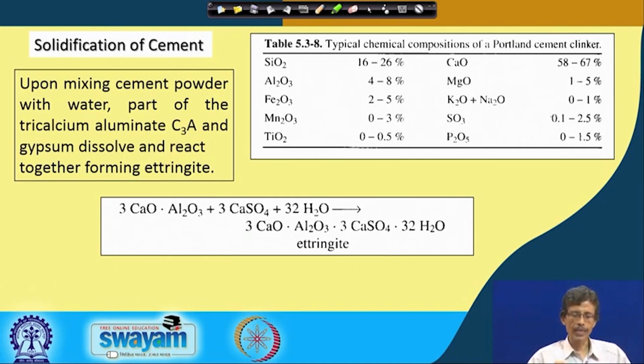That means you will have a network of silicon-oxygen bonds and a network further modified by aluminum-oxygen bonds, and sometimes you can have the corresponding sulfate material in it, because it is supplying calcium out of that, but the sulfate will be a component over there. So, that is why sulfur trioxide can be a basic component of the chemical composition. It should have up to 2.5%.